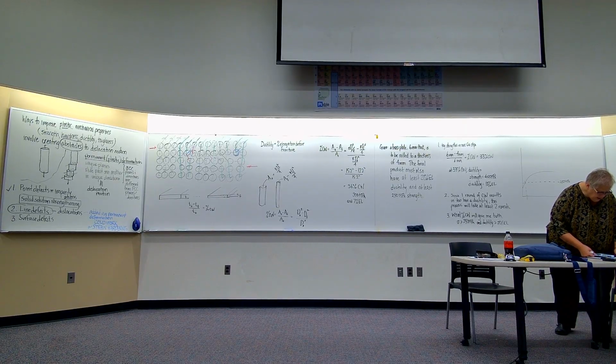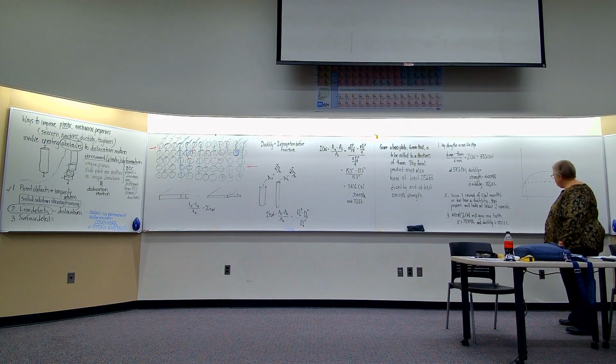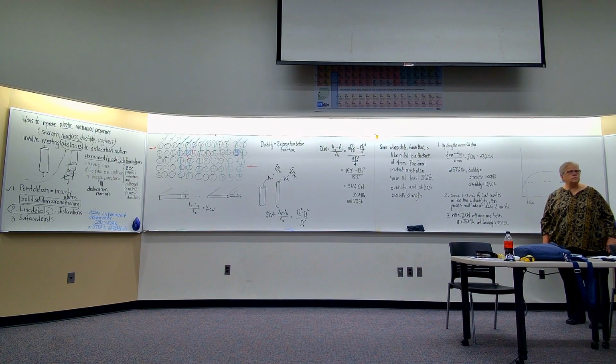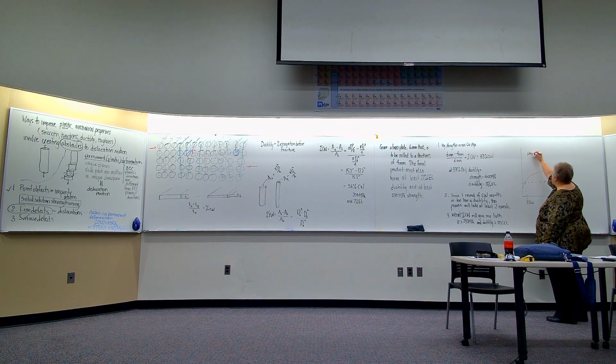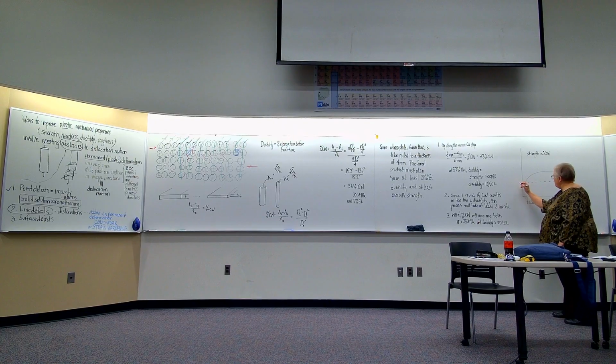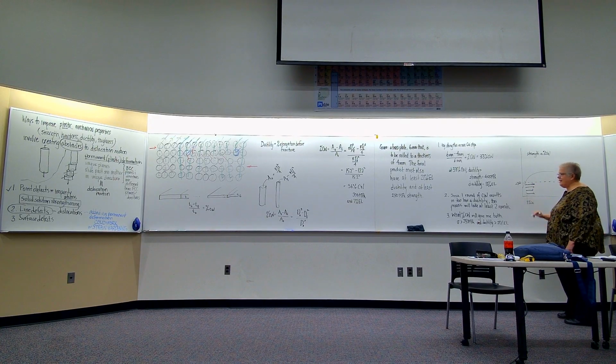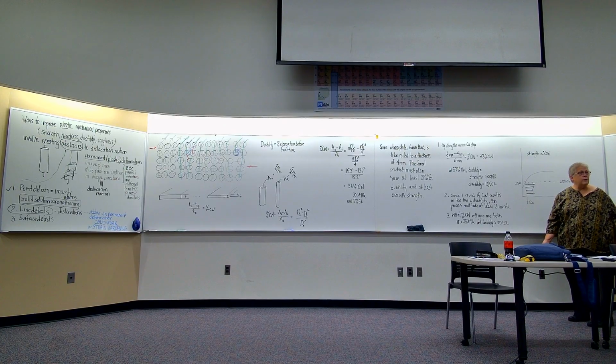I can get 250 on brass at about 8% cold work. That's where they cross. So that means I need to have a percent cold work that's at least 8% in order to meet my strength requirements.